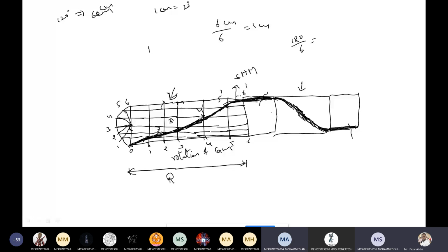The 1 dash and 2 dash lines we have to draw, sir. The horizontal points which we made, 1 dash, 2 dash, 3 dash, we have to draw, but we should not draw for the dwell and the falling period.